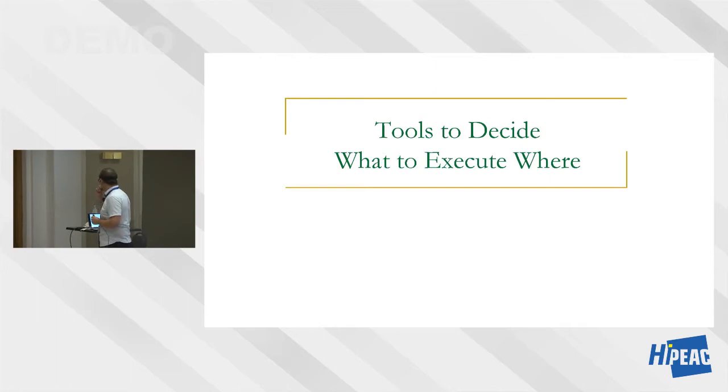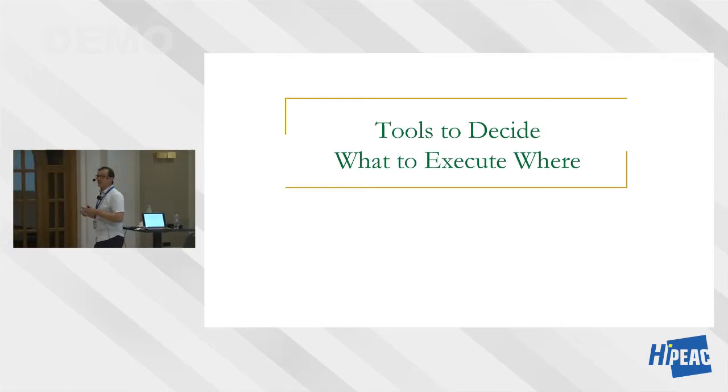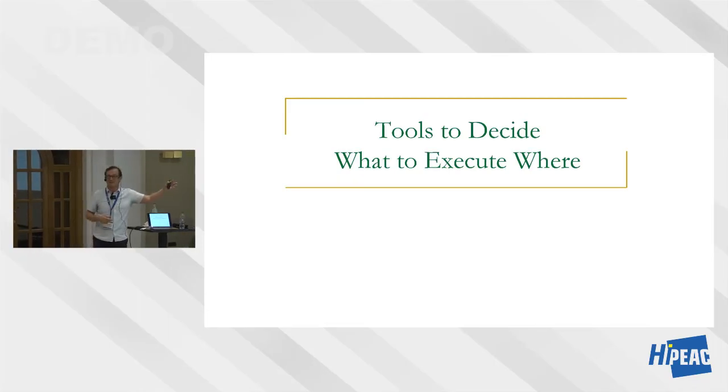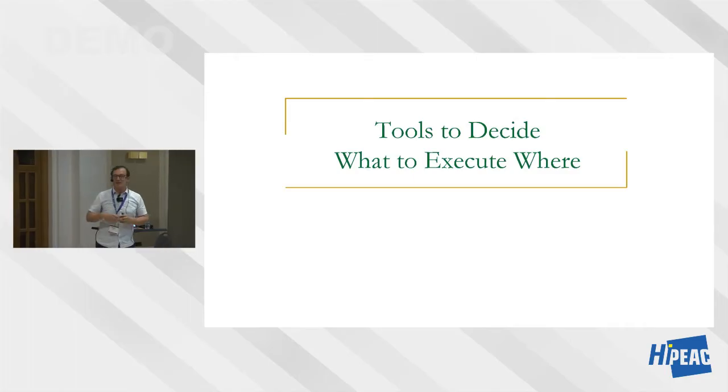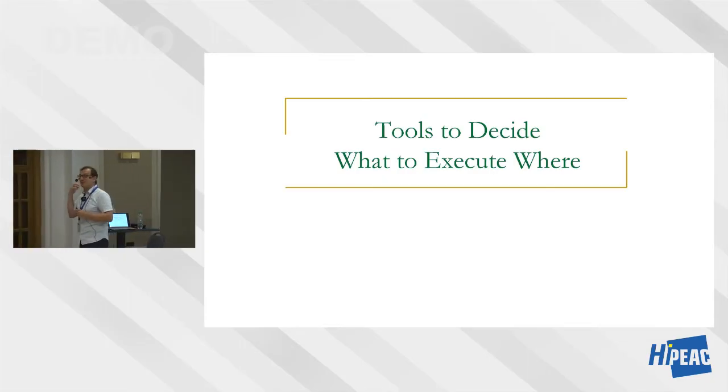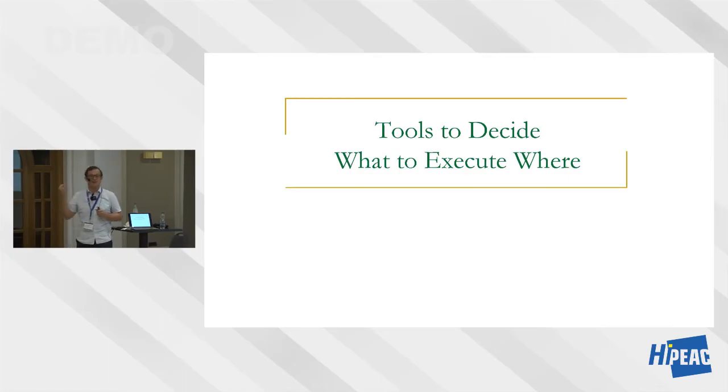Okay, so let me also mention that one thing that you do whenever you design processing in memory systems is deciding what to execute where. Because in general, executing always in memory is not a good idea. Executing always in the processor is not a good idea. You should really decide. And this is one of the difficult things for programmability as well. Who should make this decision?